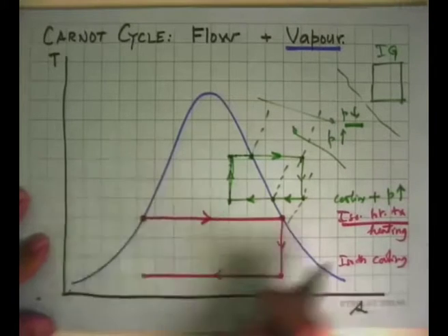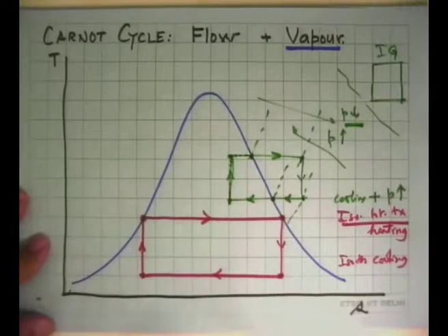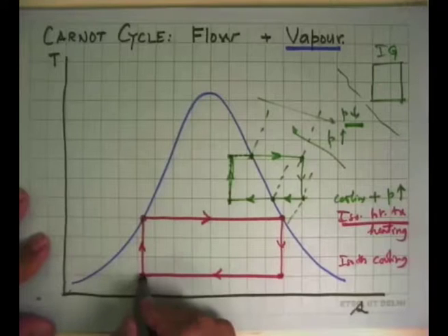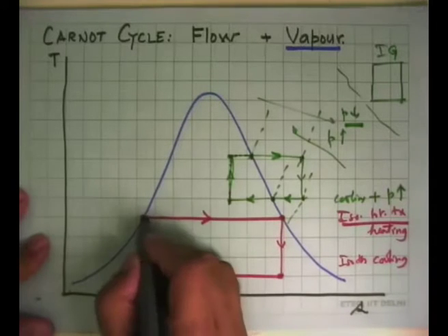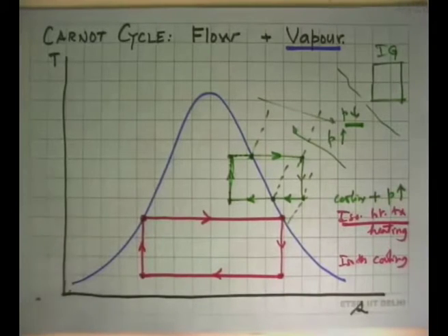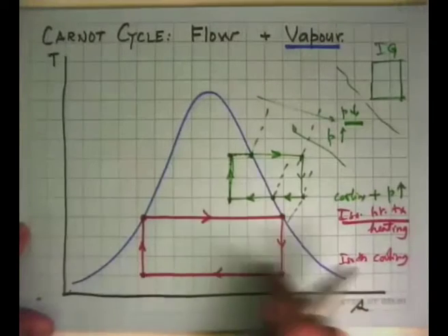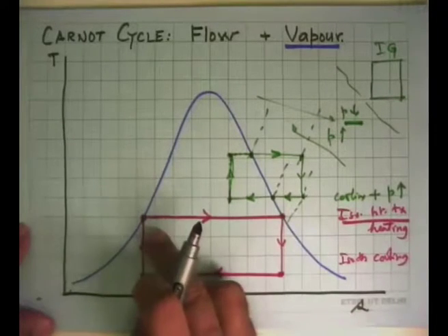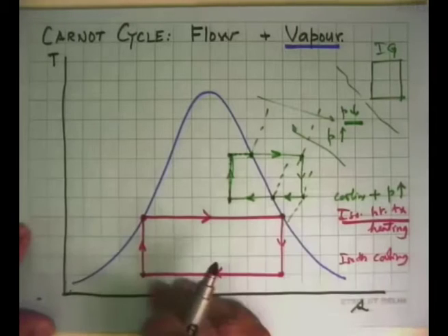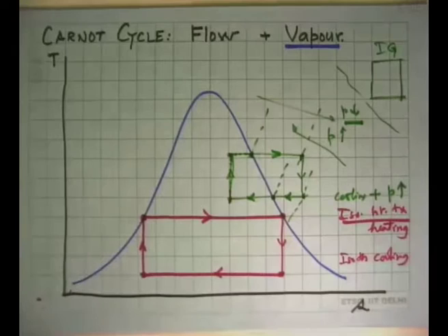And then we say, now to complete my Carnot, the last process to put is this one. And here we run into a problem. What you have here is a wet state and you are trying to compress it to make it a liquid. I cannot make this machine. So this cycle came very close, that we almost got this. These two we are able to get, this we cannot get. And so this cycle is very close to being realized, but not realizable. So what do we do next then?